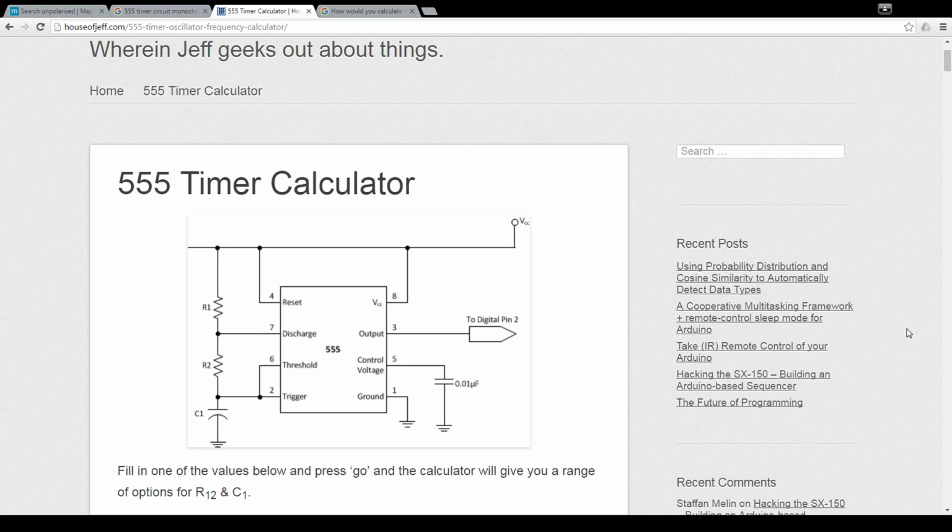But you could use a tri-state buffer, which allows the input to be pulled high, low, or pulled high by another input. Essentially, if you have several tri-state buffers in parallel, connected up to each other, then one of them can pull the rest high without affecting any circuitry. Whereas if you try to do that with normal logic gates or diodes, it doesn't quite work. So sometimes diodes and things would work, sometimes they wouldn't. So the more knowledge you have, the better.